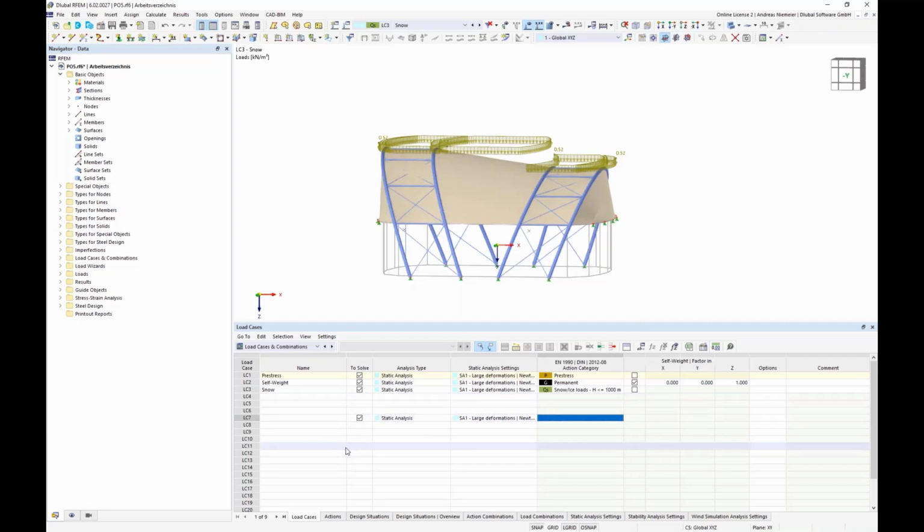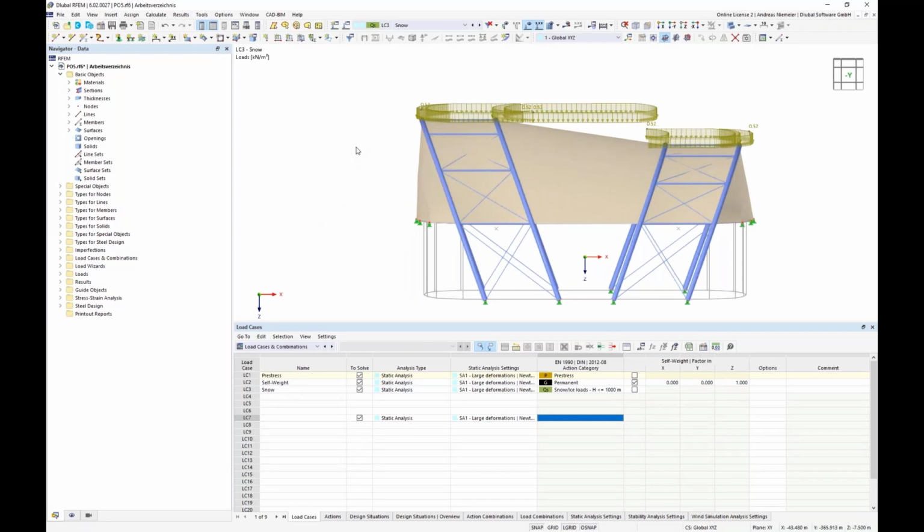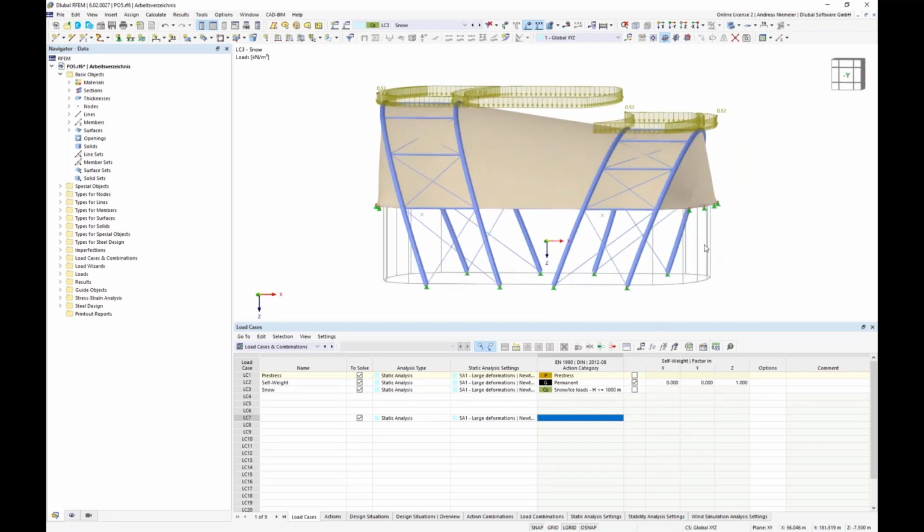But if you place this model into a wind tunnel, you have to know that the wind can maybe press here again, but it can also flow downwards and upwards. And this is not real, because here we have a building below. So if you do a wind tunnel analysis, you have to give the program a model that fits to this. And therefore we have to model also these walls inside.